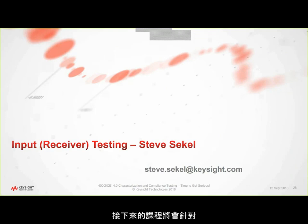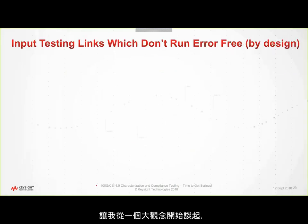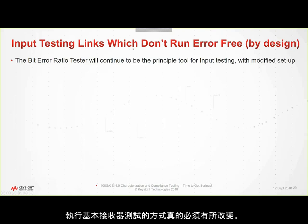We're going to focus the rest of the session talking about the Ethernet chip-to-module interface, of all the different clauses that we could be doing a deep dive into. This one, I think, we see the most questions coming out. So I'm going to start talking about just a general thing that we're running into quite a bit with people starting to work with PAM4 in the lab. Just as Rob was talking about how you need to be careful with those jitter measurements because the definition has changed, one of the things we're finding is how you do the basic receiver test really has to change when we're dealing with PAM4.